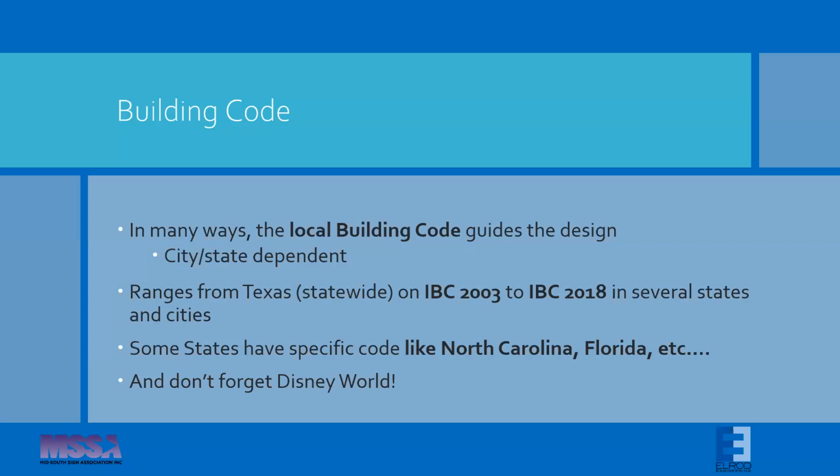One thing that surprises me is that cities do not view codes as backwardly compatible. So, for example, even looking at the 2012 through 2021 versions of the building code, you would think that those are essentially the same when it relates to signage. Some slight variations, but nothing really significant. You would think that if you had a design done to the most current one, the 2021 version, it would be good in all the other locations. But cities, if their regulations say they require the 2015 version, you have to have it done to the 2015 version. That needs to be on your drawings and on the calculations.